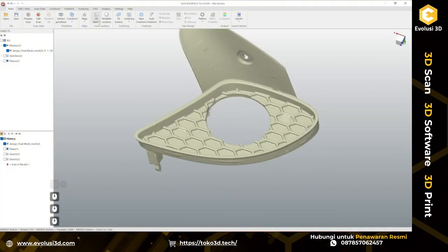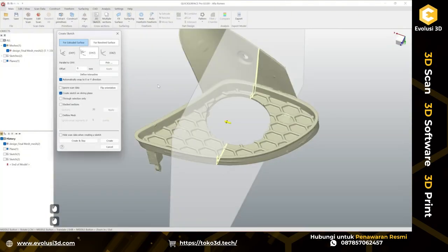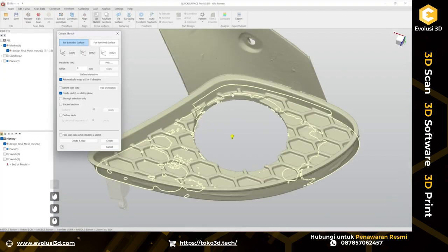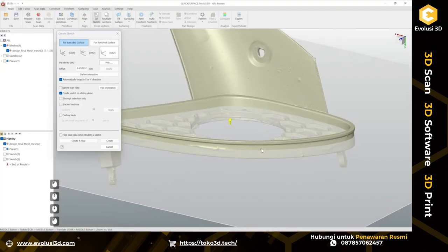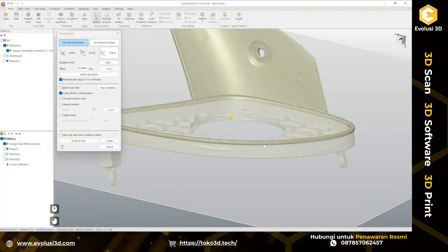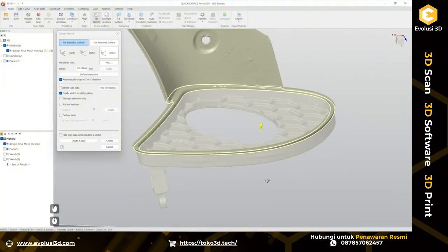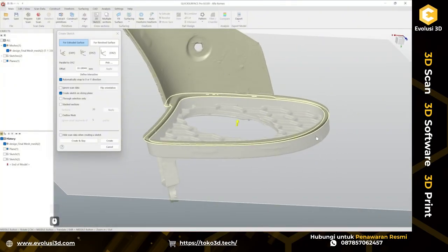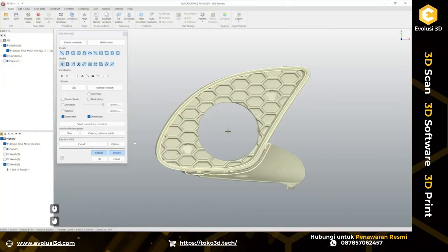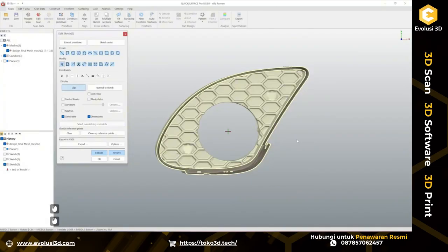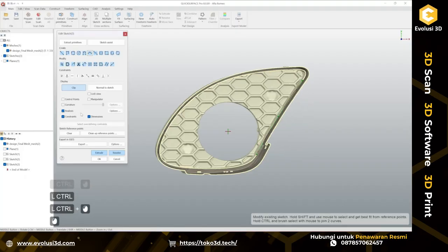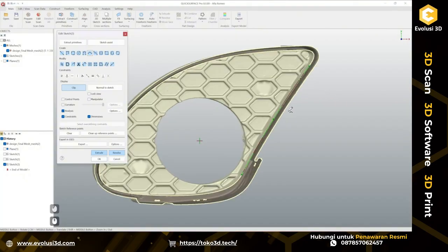So we have options. Let's say, first of all, we can create a 3D sketch here. Not a 3D sketch, but a 2D sketch by slicing our scan data to get a complete outline of this. And for example, we can start by fitting a couple of entities and try to extrude them to see how it goes. At this point, I'm going to enable analysis for entities to see how close I am here.